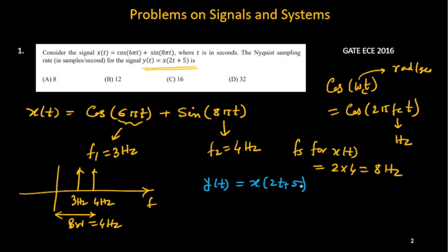Okay, so what is happening here? This addition of a constant is a time shift. That will not give you any frequency change. Frequency will remain the same. If the signal is translated, its shape is not changing. Frequency content is not changing. Could be the phase is different, but the magnitude spectrum will remain the same.